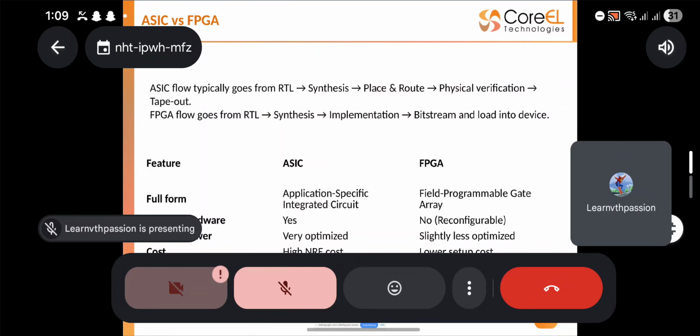Some will have a processing system and a programmable logic. It will be a combination of both on FPGA boards. Some will be only the programmable logic board. And when you hear FPGA, inside the FPGA architecture, there will be DSP slices, lookup tables, CLBs, configurable logic blocks, and under that you will have IOs, inputs and outputs. Various things will be coming. These are all the resources available.